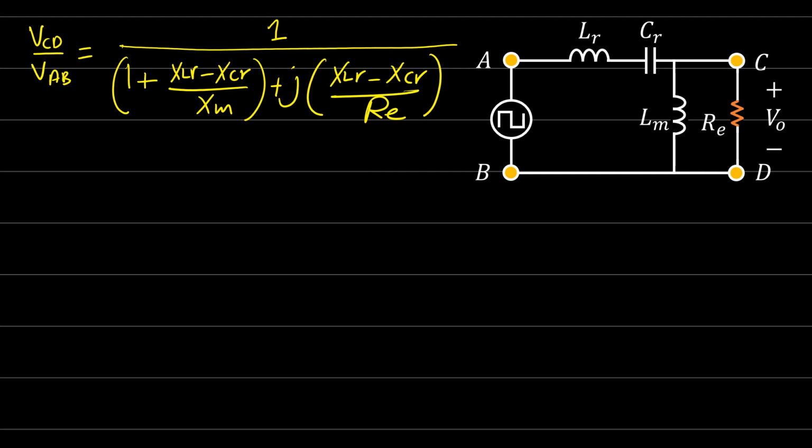VAB and Vinput. So Vout first harmonic over Vinput first harmonic is equal to how much? The input will be plus VDC, minus VDC, not VDC over 2. So this square wave VDC, and its first harmonic is 4 VDC over pi, not VDC over 2 over pi, no. It will be VDC.